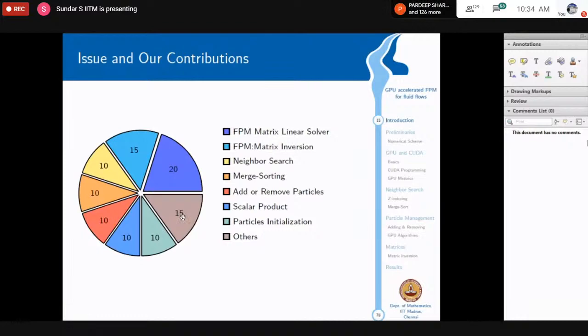If the total computation is 100%, now 20% goes to the FBM matrix linear solver. I told you there is a linear solver which we need to do. The linear solver through the finite point set method, grid tree method, takes 20% of my computational time. FBM matrix inversion, you will understand I need a matrix inversion at every time step, at every point. That takes 15% of my computational time. I'm doing a lot of neighborhood search. That takes 10% of my computational time.